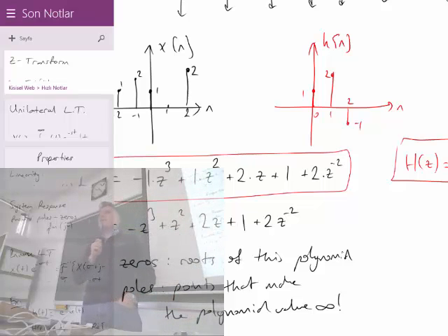So now we have an alternative of performing convolution, right? We just transform our discrete time signal into a polynomial. We convert the other signal, discrete time signal, to another polynomial. We multiply those polynomials. And that polynomial multiplication result will correspond to the convolution automatically. So convolution is the same as polynomial multiplication.